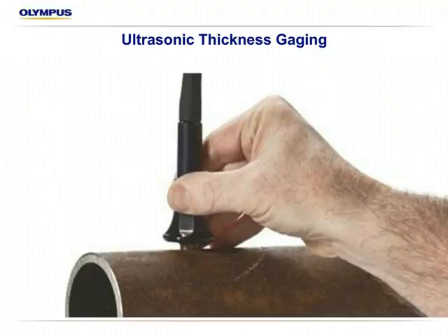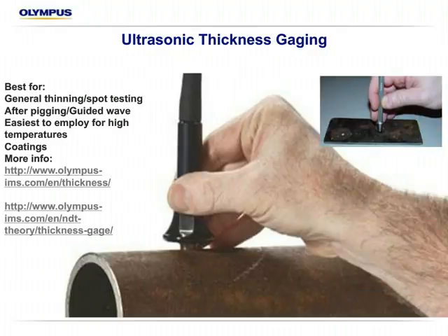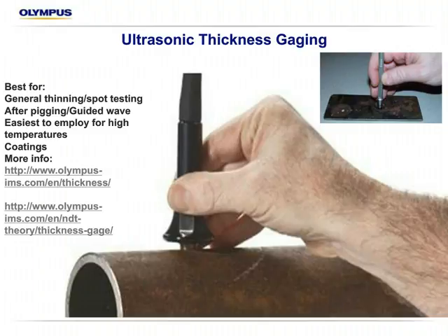Just a mock-up of dual element on a pipe, looking in that case mainly for internal corrosion. And if we were looking for external corrosion, or we could visibly see external corrosion, we have special small-point sonopens and other things that can go down into the pit and measure the remaining wall as well. So the basic concept's the same either way.